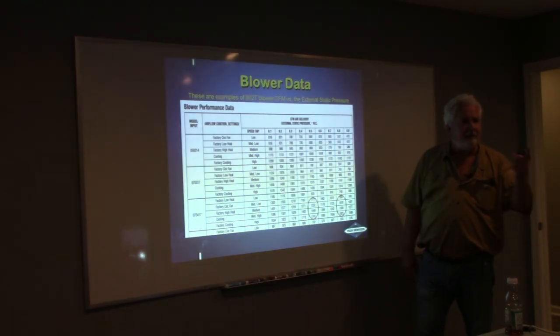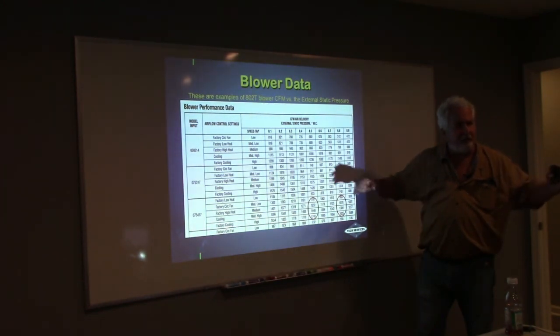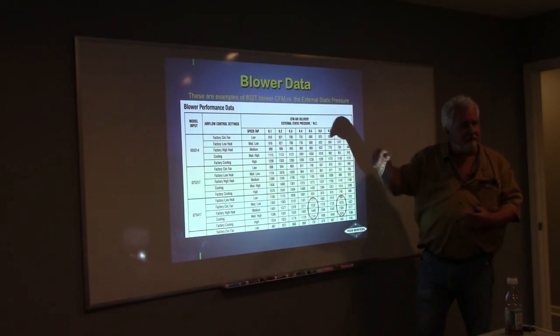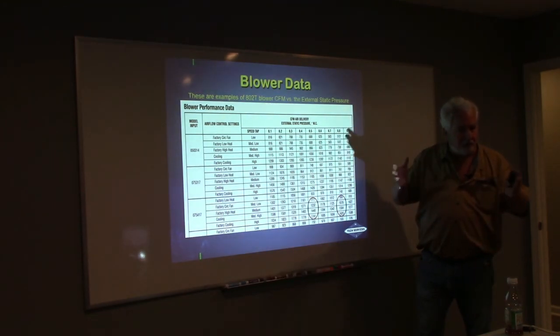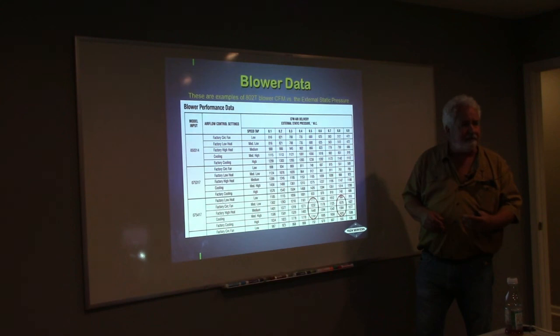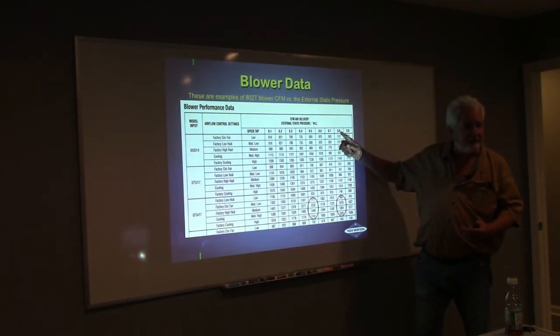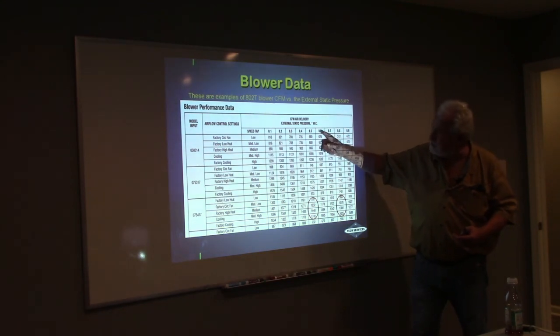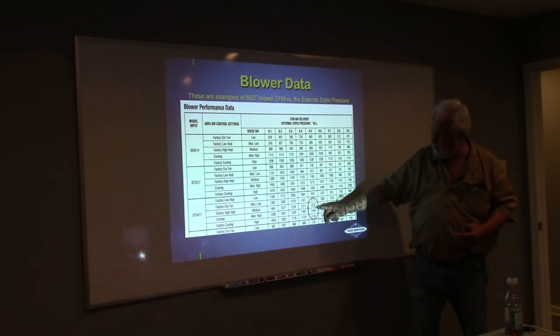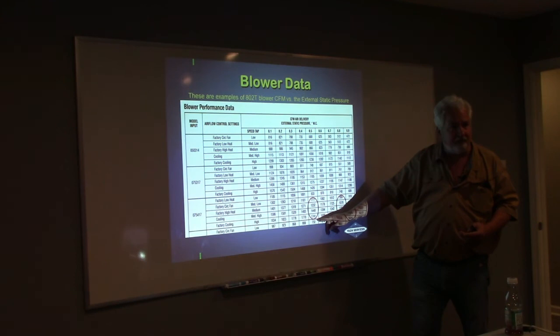How about put the turning vanes in? How about straightening out that duct so it's not doing this? How about sizing the ductwork large enough to get the air through there? Maybe get rid of that pleated filter she got from Home Depot. All of those things are going to reduce this static, is that right? If I reduce the static, I'm good, is that right?